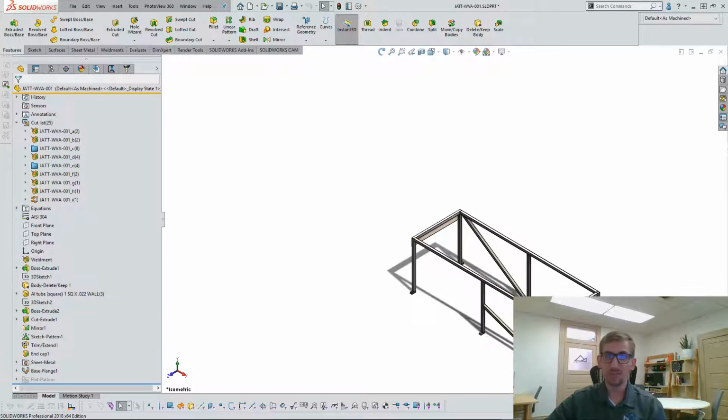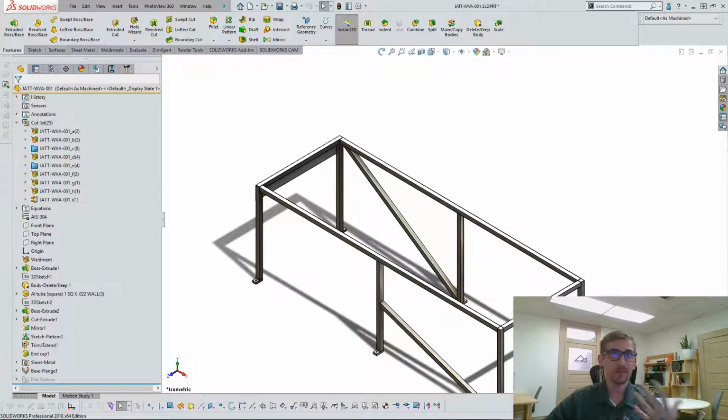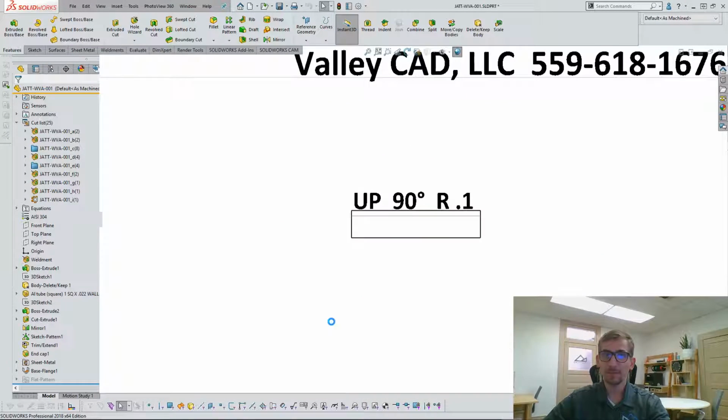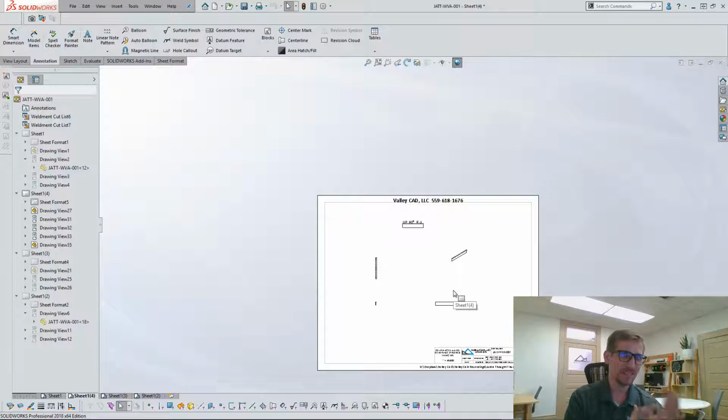And I can add as many sheet metal bodies as I want to this Weldment. And I can update it as I see fit on there. So I hope this doesn't make it a little more murky. Like I hope that this can help you out in saying, okay, this is when you use Weldments, this is when you use Assemblies. Ultimately, if it's something that needs to get welded to each other and becomes one component, you should use a SOLIDWORKS part file and you should use Weldment features in that. Weldments and sheet metal, okay?